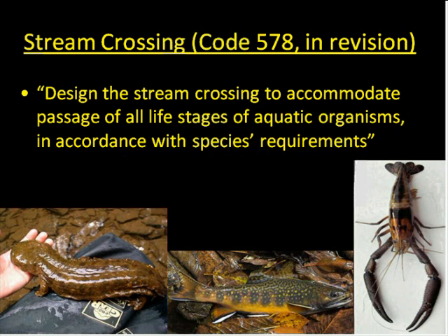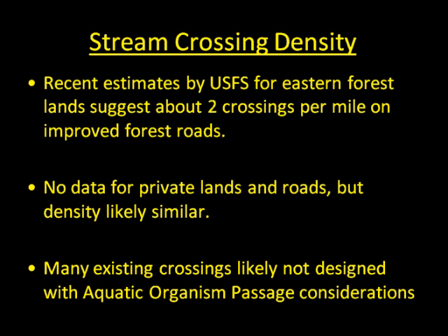Although 578 contains a number of criteria that dictate the type, appearance, and design specifics of a stream crossing, I'd submit that using a geomorphic approach, that is, trying to place the site in its watershed context and designing a crossing to fit within that context to the fullest extent possible, will provide the best mix of passage conditions for all the aquatic critters we may encounter and long-term stability in the face of a full range of stream flow and the materials it carries.